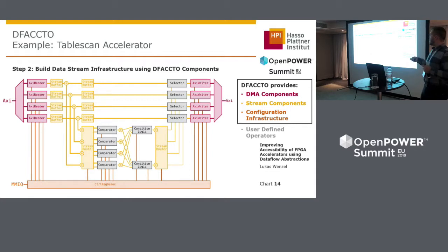So in this case, the selector would need to wait for the corresponding Boolean value of taking the row or not taking the row, and would hold this data stream in some kind of wait state until it has this information. And the latency of this pipeline would actually limit the bandwidth of the entire design, and this is not desirable. So we need a stream buffer that is exactly as long or longer than the latency of this pipeline here. But one positive point is that we can use predefined components for that. We just need to keep in mind what their semantics are.